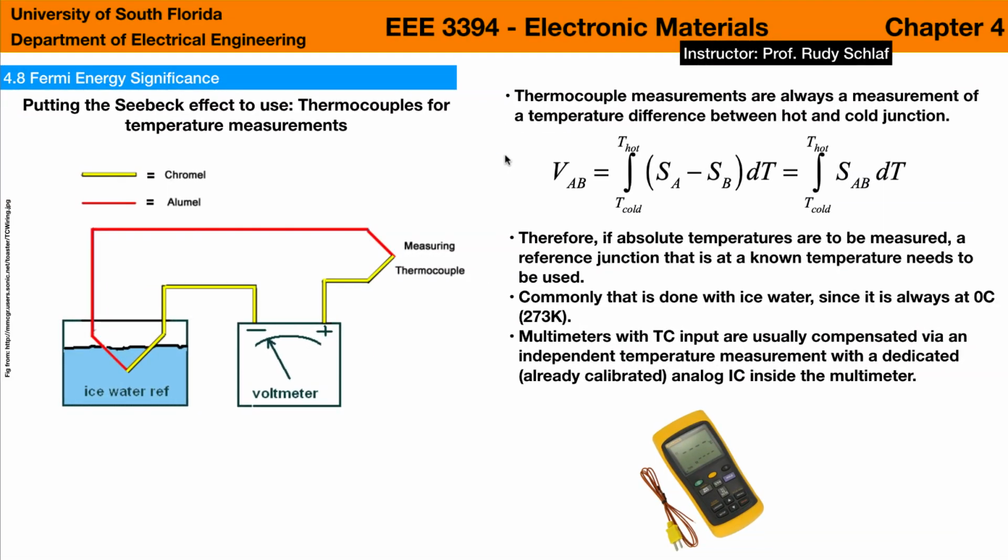It is important to realize that thermocouple measurements are always the measurement of a temperature difference, right? If you look at the integral, we always integrate from temperature cold to temperature hot. So we only get a voltage that is depending on the difference between these two temperatures.